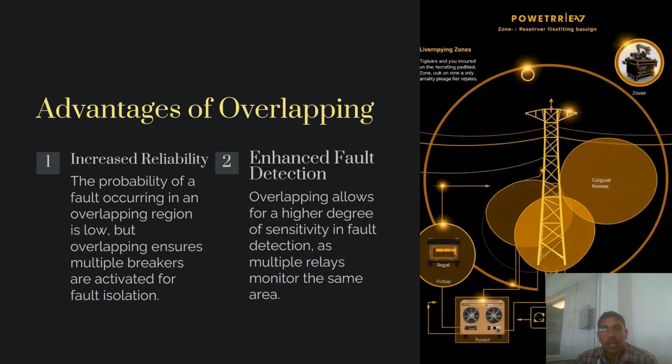As concerned with the advantages, we have two major advantages here. One is increased reliability, another one is enhanced fault detection. Increased reliability means that one or more elements are connected, which we call overlapping. This ensures multiple breakers are activated for fault isolation, not a single breaker. So it is going to provide more reliability and recover as quickly as possible from whatever fault happens here.